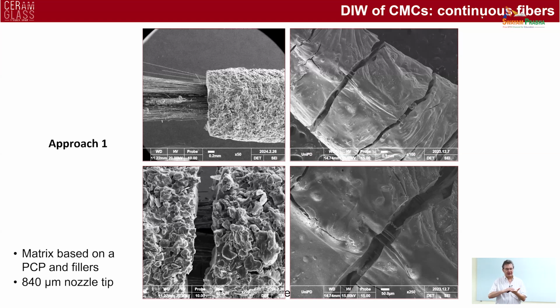And so you have a fiber sheet, and you pre-preg the sheet with the pre-ceramic polymer, and typically also some particles. And then you simply lay your fiber sheets one on top of the other. You press, you cross-link, you then pyrolyze. And you will certainly end up with a cracked matrix.